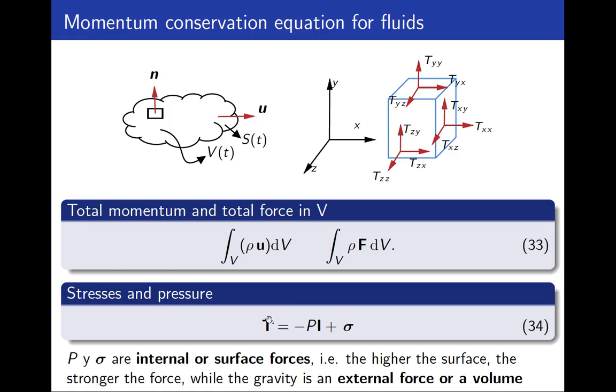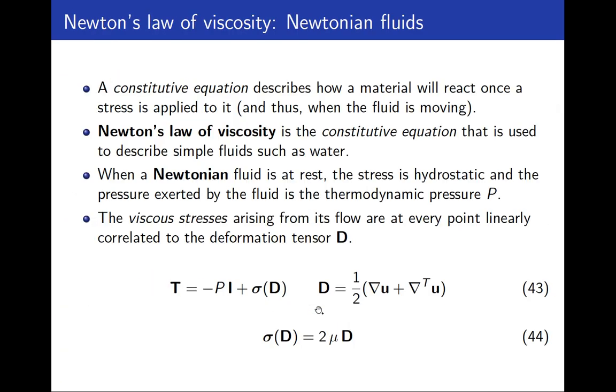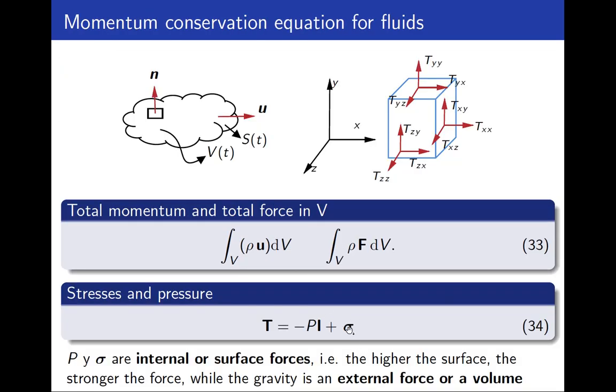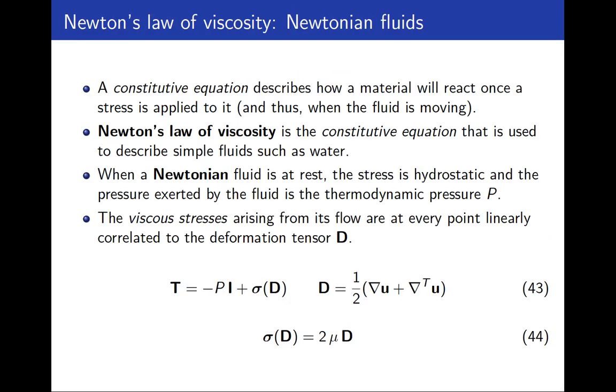So the only stress that is present in the fluid is the fluid pressure, the hydrostatic pressure. And then, you remember that I mentioned that we were going to explain this tensor, this mathematical representation of the stress tensor of a specific fluid. So for the Newtonian case, for simple fluids, this stress tensor, which is associated to the dynamic contribution to the flow, is going to adopt this form.